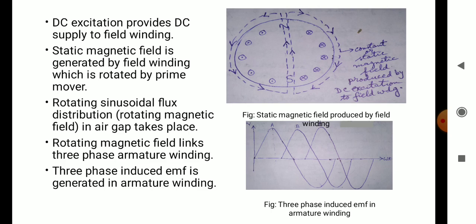The direction of the DC current in the field winding can be seen by dots in the left hand side of the field poles, and in the right hand side of the field poles the current direction is represented by cross. Then for this current direction in the field winding, if we apply the right hand thumb rule, we can easily obtain the field direction for this given field current.